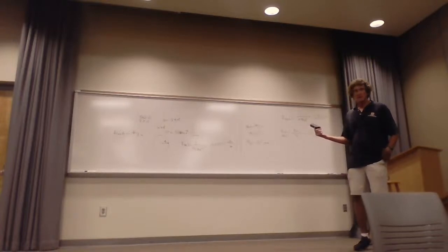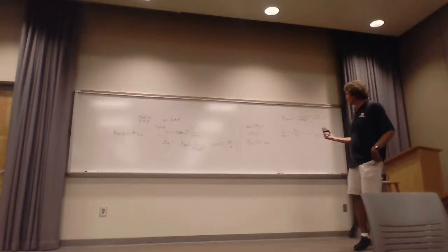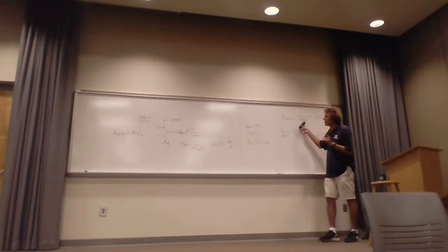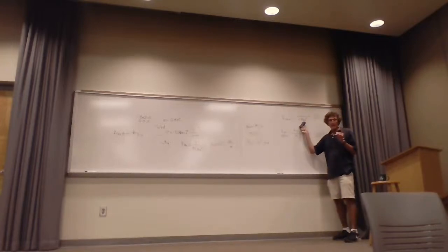Is the one on top AC? No. This is the resistance for one strand. If you have 19 strands in parallel, you divide by 19, right? Just think, if you have two resistors in parallel with the same value, you take the value divided by 2, then 3, then 4, and so forth. You divide by the number. You've got 19 in parallel, right?